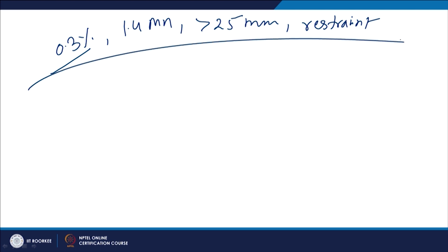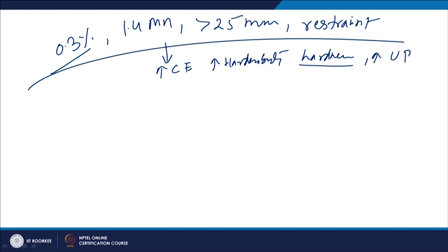So, if these conditions for the welding are present, as for the composition and the fabrication conditions, then there can be various problems, because the high carbon as well as high manganese lead to higher carbon equivalent, higher hardenability, and so the formation of martensite of high hardness, which in turn will be increasing the underbead cracking tendency of this kind of steel while offering really good yield strength.